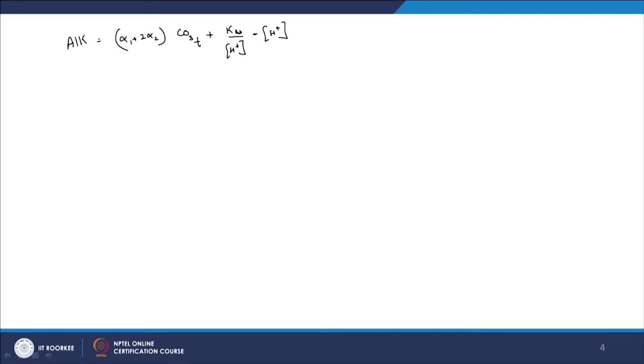So let us say now this is for the mixture, where we mixed up 1 and 2. How do I go about calculating it now? For this case, I can calculate alkalinity. How do I calculate alkalinity? I can say V1 into alkalinity 1 plus V2 into alkalinity 2 is going to be equal to V3, the volume of the mixture, into alkalinity of the mixture. And we know volume 1, alkalinity 1, volume 2 and alkalinity 2. Vm is nothing but V1 plus V2, obviously.